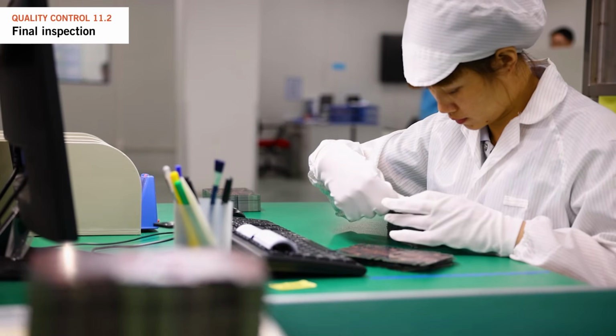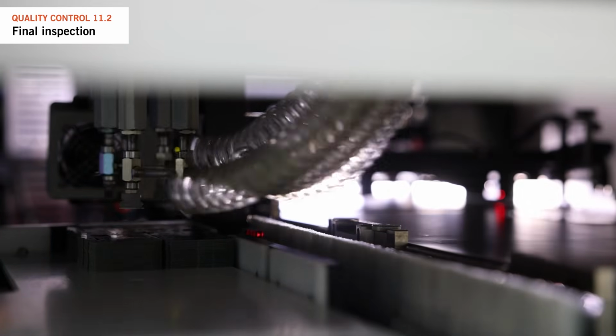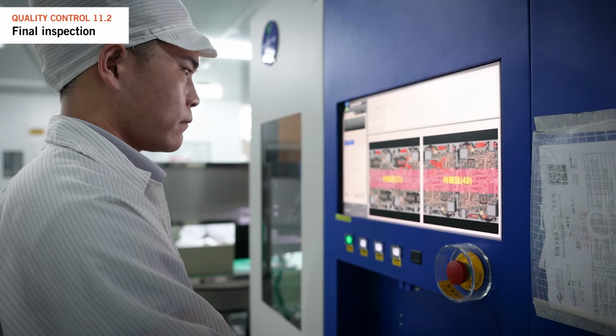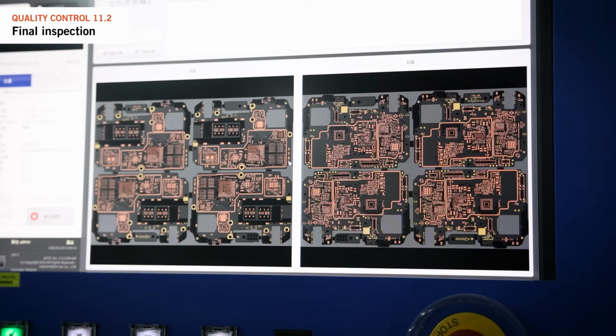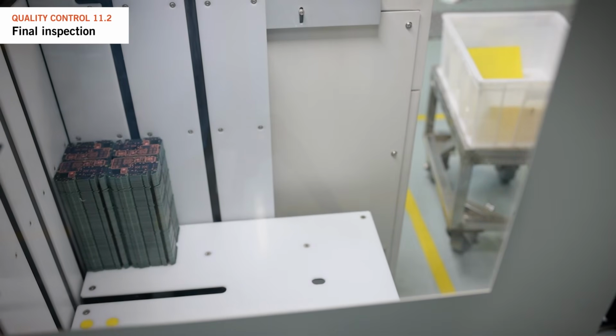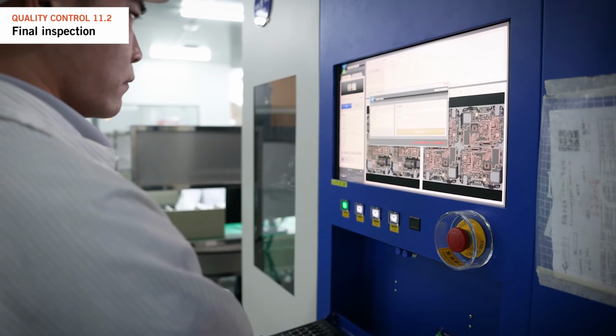Factories use both manual and automated visual inspection, AVI, to inspect 100% of the PCBs supplied to NCAB and our customers. The manual inspection is straightforward, while AVI, under high magnification, compares images to highlight discrepancies or concerns automatically. AVI is crucial for detecting issues in smaller PCBs, but the inspector's skill is still essential for judgment.